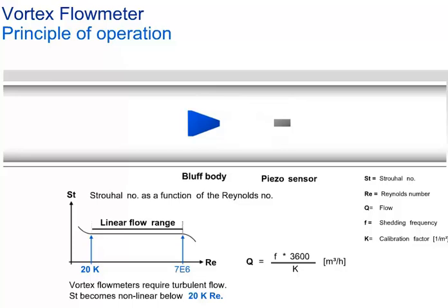The density of the substance of the volume has an impact on the intensity of the pulse, but no impact on the pulse frequency. The higher the medium density, the stronger the signal from the sensor. This is why the measuring dynamics in gas and steam measurement change with the actual density of the medium, which is a function of standard density, pressure, and temperature. The K factor provides the volume information for one pulse hitting the sensor.